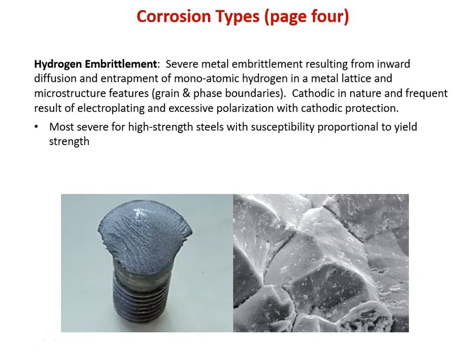And so, oddly enough, in an attempt to prevent stress corrosion cracking, we will often apply what's called cathodic protection. And if it's misapplied, we can actually take a material from being susceptible to stress corrosion cracking to being susceptible to hydrogen embrittlement. That's something we can manage, but it's important to be aware of it.